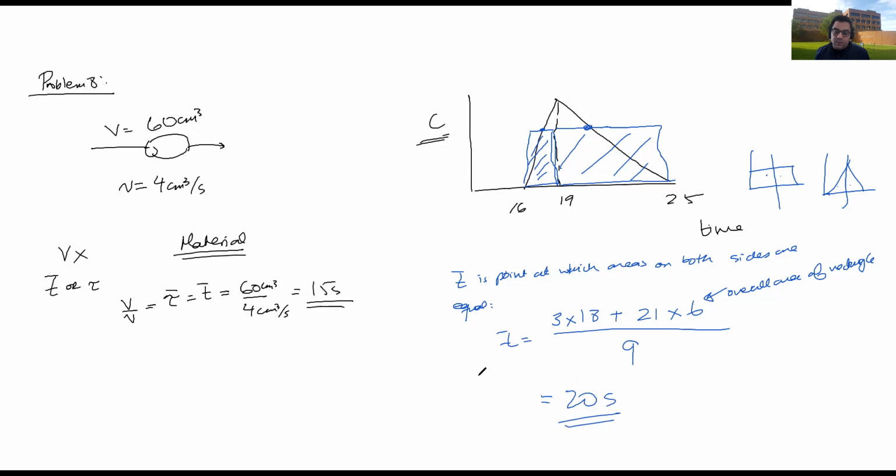Okay. So you see this is different than this. So the results are not consistent, and there's something wrong with your system. You need to take a closer look at this reactor. Is it leaking? Is something going on? Do you have a phase change in the cooling jacket? What's happening here? Why don't they make sense? Why is the mass balance not closing?